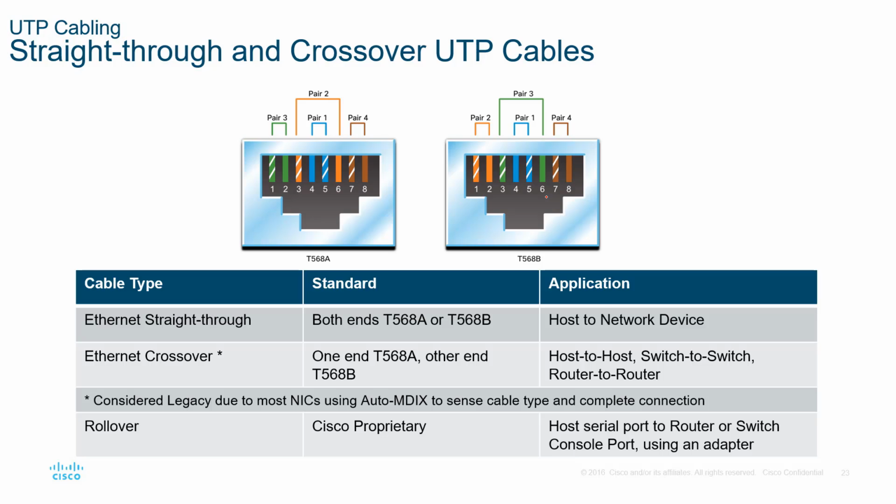If we want a fully functioning cable, we need to make sure all 8 pins are correct. But as long as 1, 2, 3, and 6 are connected, basic communication will occur. We're not talking fast, we're not talking 100 megabit, gig or 10 gig, but a basic 10 meg-ish connection is definitely doable with 1, 2, 3, and 6.